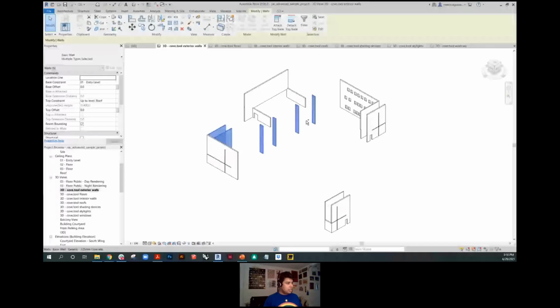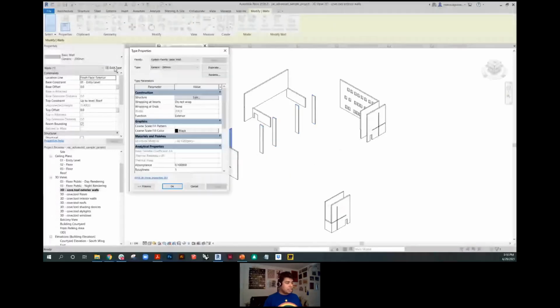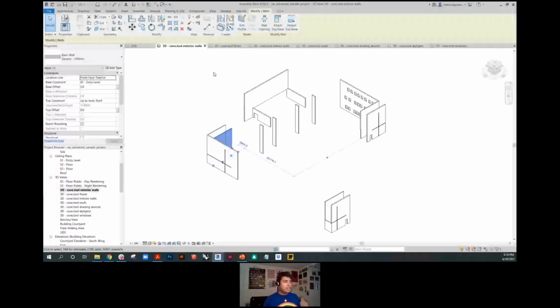This is because we're using a category called function of the object in order to determine whether it's interior or exterior. So anything marked exterior and is part of the conventional wall families will go to the exterior walls layer, and then anything marked interior goes to interiors, and other categories or other parts of the 3D views are also using those properties to filter geometry.